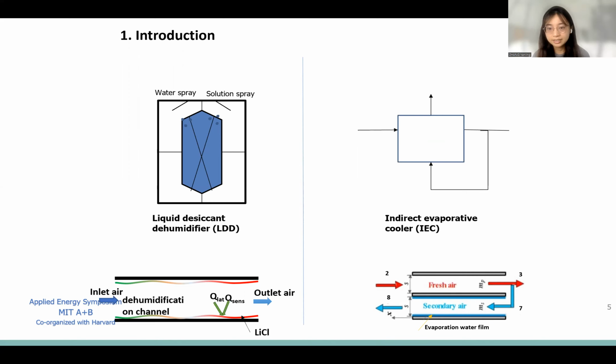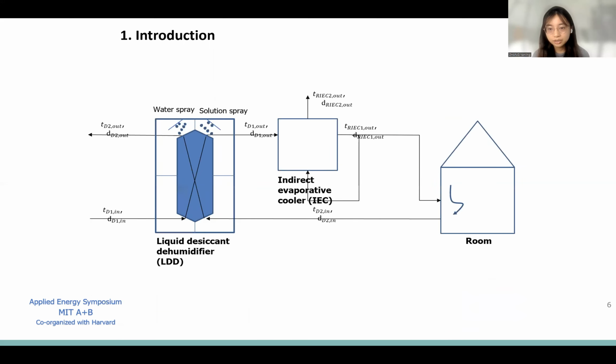For cooling, EC is well recognized for effectively handling the sensible heat load. And to deal with the latent heat, the liquid desiccant dehumidification stands out as an effective technology. So, if those two components combine together into a system, it might achieve freedom from harmful CFC-based refrigerant and have giant cooling potential. Shown here is the newly proposed internally cooled desiccant enhanced evaporative cooling system model, which is also the ICD-VAP system. In this system, the application of return air will be optimized.